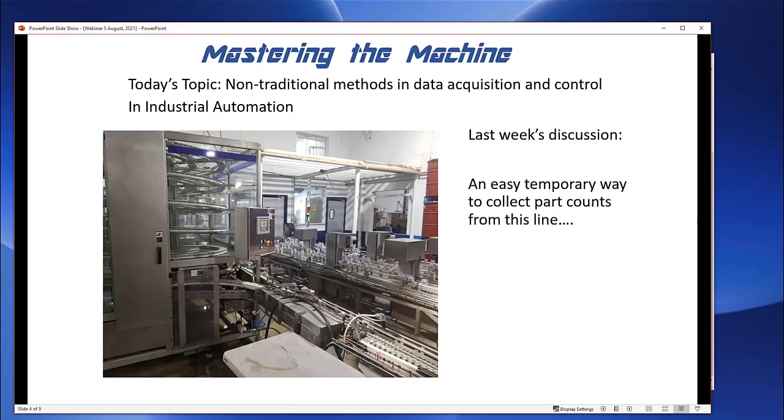So for instance, I saw today when I was doing a little research for this, a little box that you can hook up to your motor and transmit directly to a PLC that is an analog value. And of course, with what we talked about last week, the only thing you're going to get from that is pretty much amplitude. You're going to know, okay, I have more vibration or I have less vibration. But some of the things Phil showed me is that when you analyze those waveforms, you can find out, is it the bearing that's going to fail, or is it the windings that are going to fail? So why don't you tell us a little bit about what you do there?